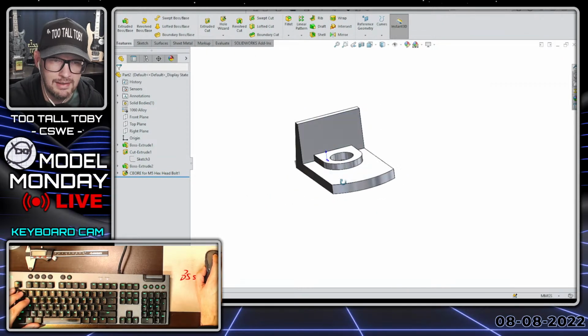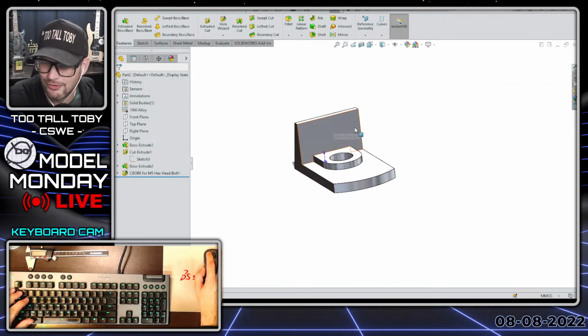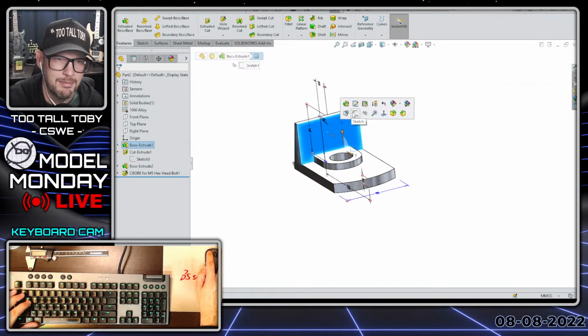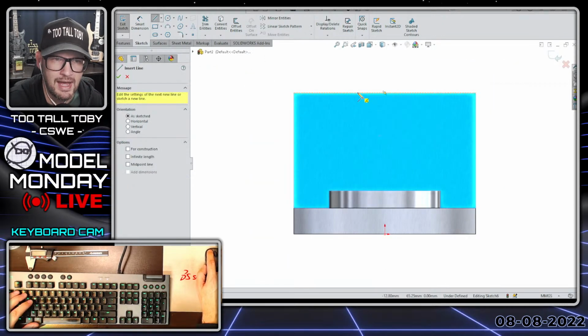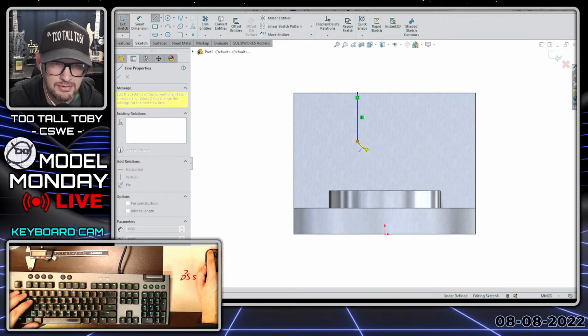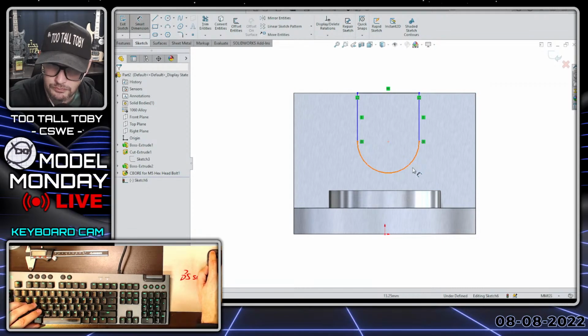So again, I know that's a little bit of an advantage for SolidWorks users over some of our other users, but maybe in their CAD packages, the hole wizard works similarly, or if not, you just have to learn, it's a pretty standard C-bore call out, so you just have to learn how to read it and then what the order would be in your CAD package.